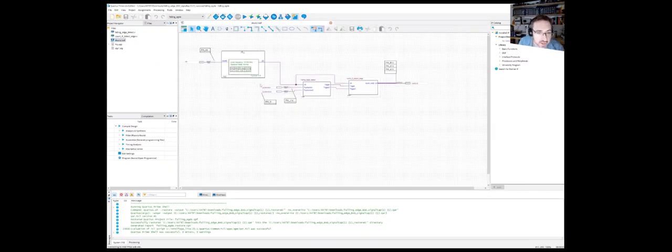So all I've done with this design is I've added a phase locked loop, and that PLL is decreasing the clock frequency to 2 megahertz. So this point here is a 2 megahertz clock. Now this input clock, of course, is still 50 megahertz. And the reason I've done this is so I can actually visualize the trigger in Signal Tap.